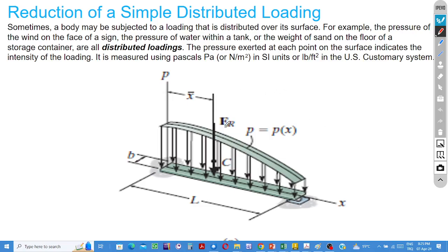And at its special location, the resultant force can represent the rotation effect of the distributed load. This location is equal to the location of the centroid of the volume of the space which is under the load curve.